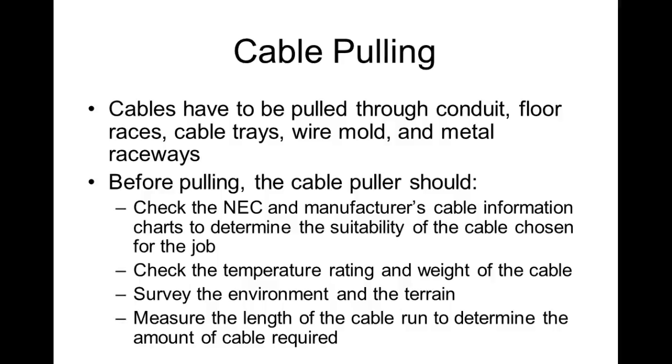Before pulling, you need to check your National Electrical Code charts to determine the suitability of the cable for the chosen job. So we're making sure we put the right current in there. You pull all this wire, then you get in there and realize you pulled the wrong gauge wire. That's going to be awful, right? Or you don't use the right jacket on the wire. You run it through an environment that wire is not rated to.